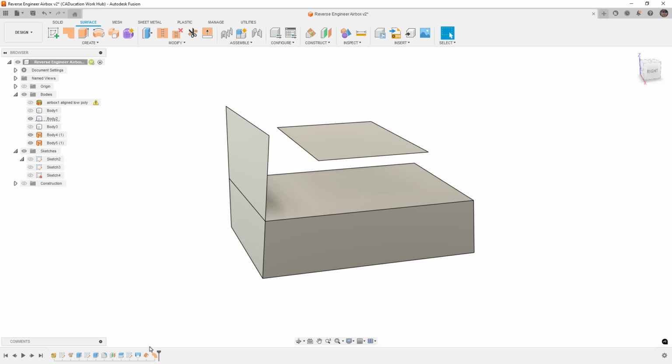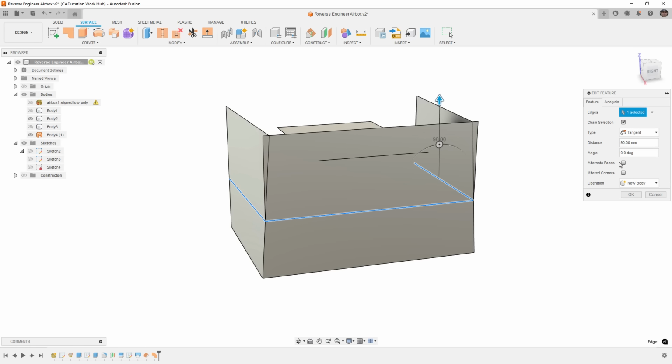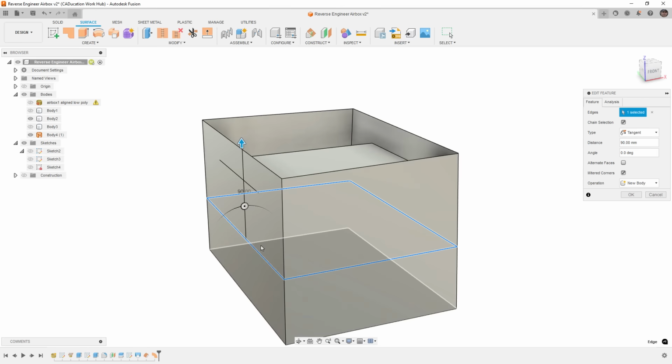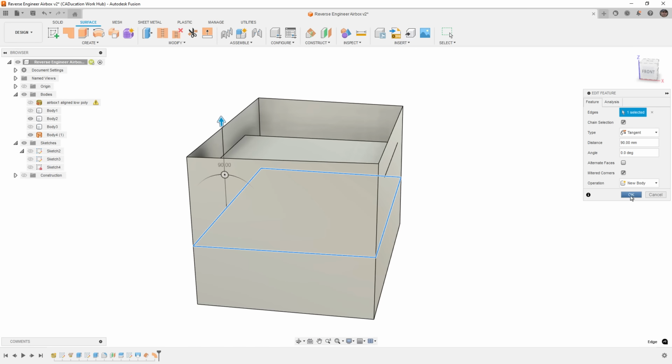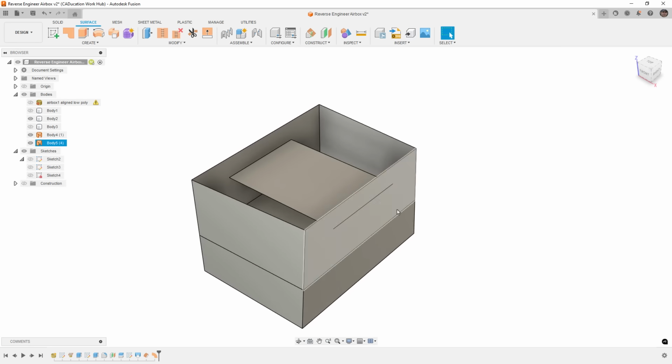So this tells me I can go back to this original ruled surface, hold down Control, select these edges, and miter the corners. Actually, while we're at it, let's go ahead and grab the front one as well. We'll just do all of them. Go crazy. All right, so now what I have is basically this box.